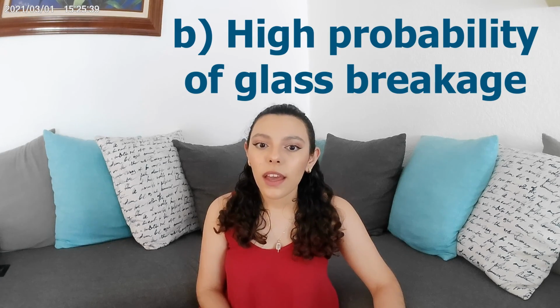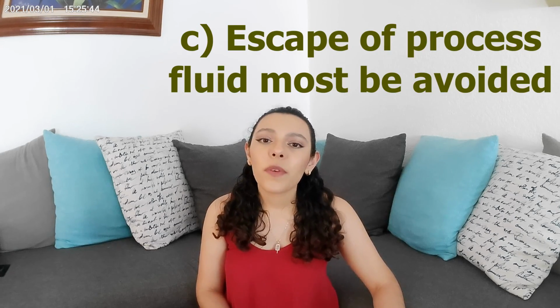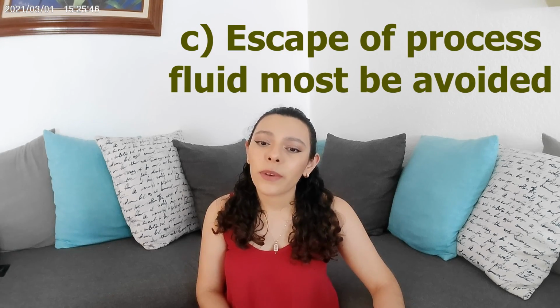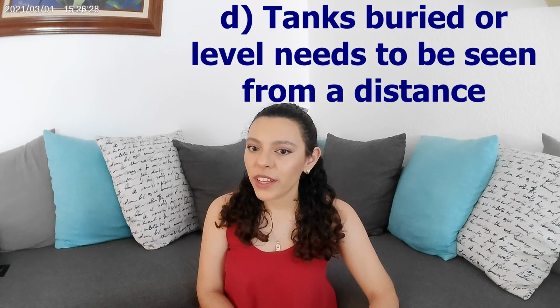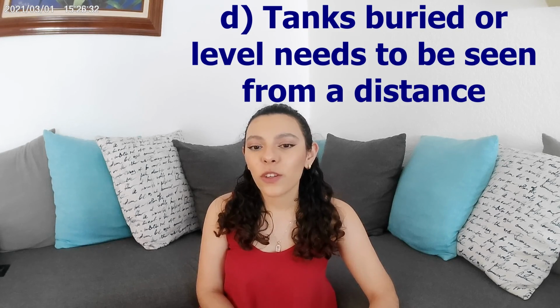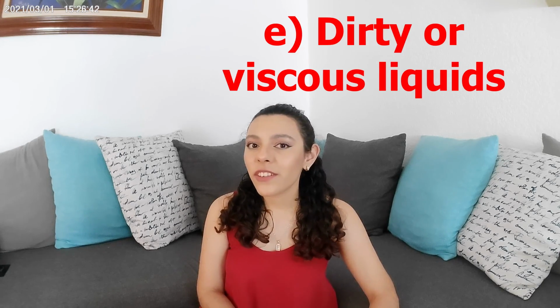A. The pressure is above 0.5 bar. B. There is high probability of glass breakage. C. The escape of toxic gases, flammable liquids, etc. must be avoided. D. The tanks are buried or the level needs to be viewed from a distance. And E. When the liquids are dirty or viscous.